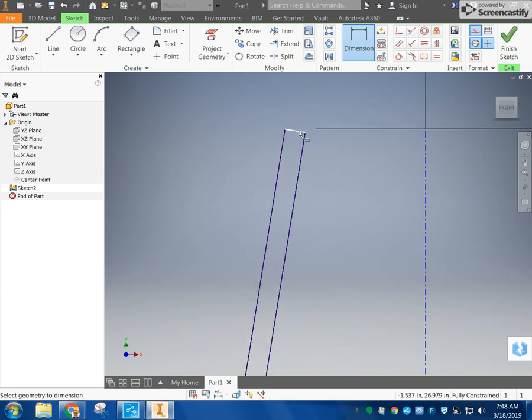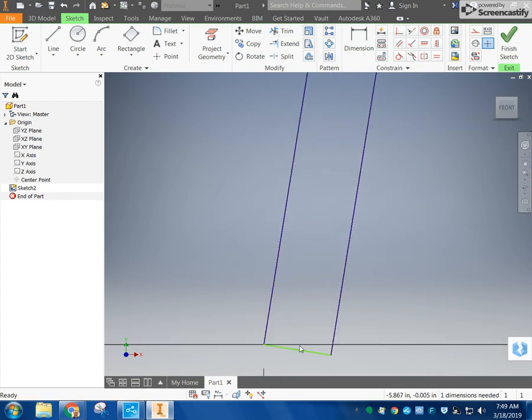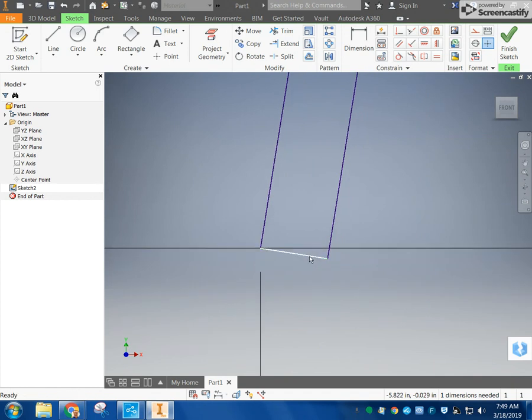So the part I don't like about this is this top part. You don't really have a flat line coming across. And as you'll see, if I try to make a flat line coming across, it's going to be a little bit hard to do because if I use the extend tool to extend this out, I can come back in. But as soon as I start deleting and trimming this stuff, then sometimes I run into problems. And you see down here, now this line doesn't know kind of what it needs to be set up to be. So I'm going to just make it horizontal.